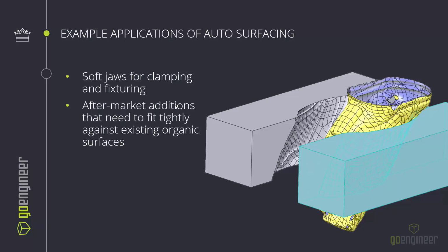So having another CAD model that accurately reflects the real world shape of the part for your fixture is going to be a lot more helpful than the idealized pre-molded version of that part. So you can then take that model and do things like make these custom soft jaws for this part where it wraps into every little surface nook and holds the part super securely.